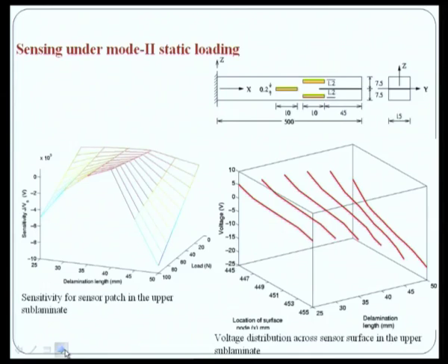So, this is another way where the sensitivity is done, for the patch in the upper portion of this sensor here, and the same thing is the voltage distribution. This is the sensitivity. So, we see how the voltage, in most cases, has a linear variation. In some cases where the level of stresses is very high, especially in this sensor, we see a significant nonlinear variation. So, basically what we are trying to see here is how we can use piezoelectric material for sensing applications.